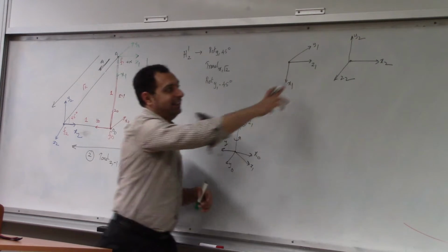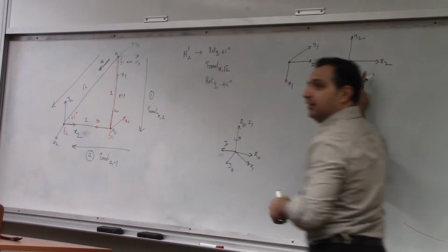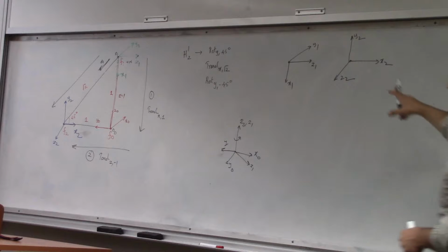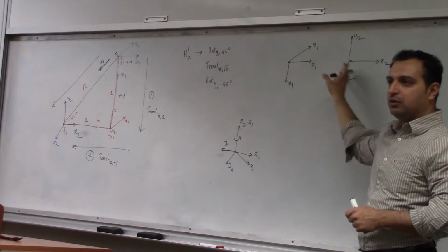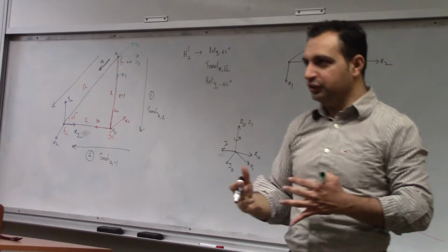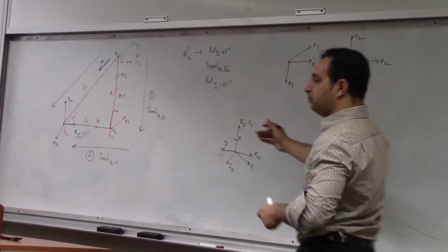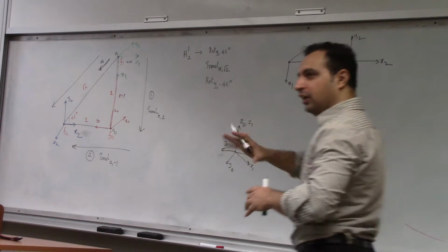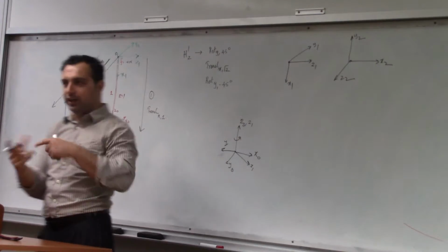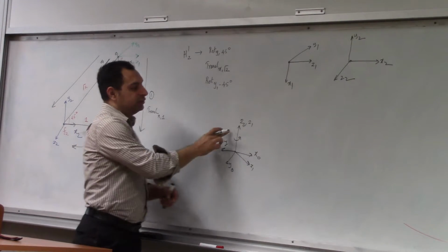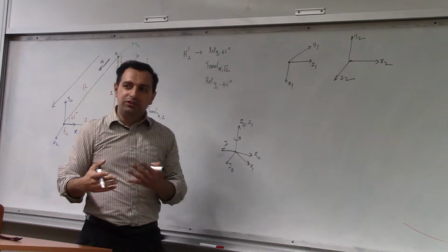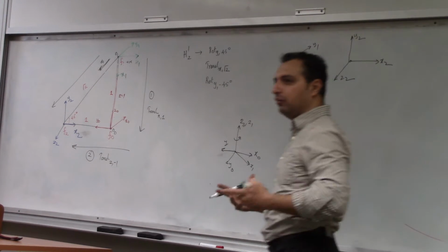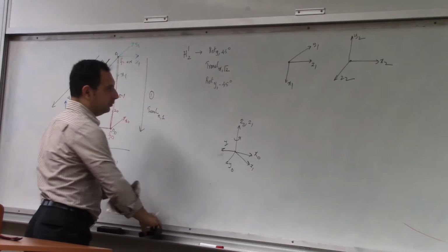So if I see that one of the axes is already aligned, that means I need only one rotation to move it back, right? In this case, none of the two axes are aligned. So it will take more than one rotation. Because whenever you rotate about a particular axis, unless it's a fixed axis rotation, in which case all three will rotate, then you need an independent axis or a k-axis, right? So long as none of the two are aligned, you'll need more than one rotation to bring them into overlapping frames. Otherwise, it's not going to happen.